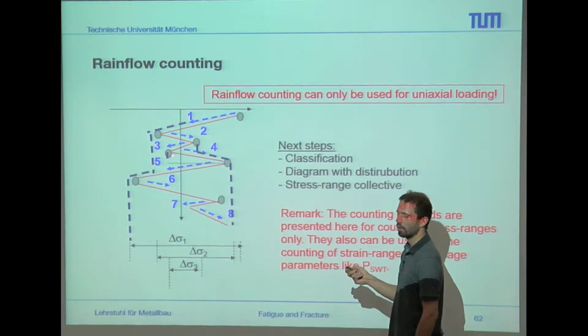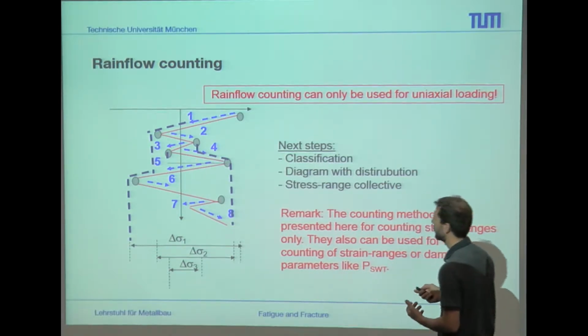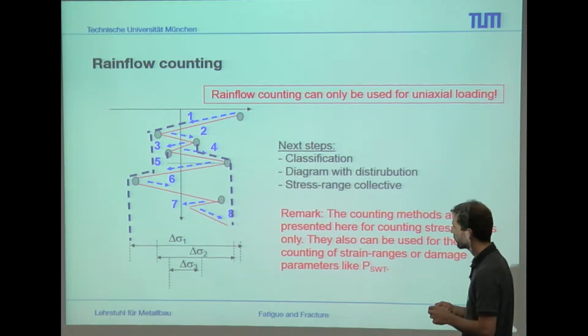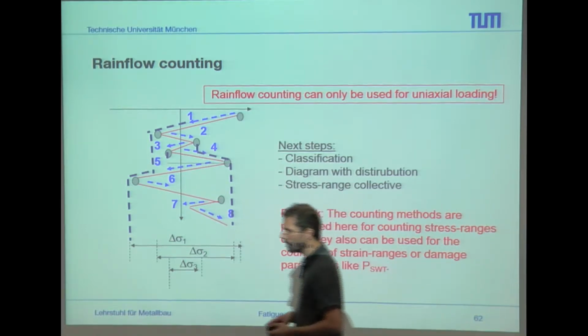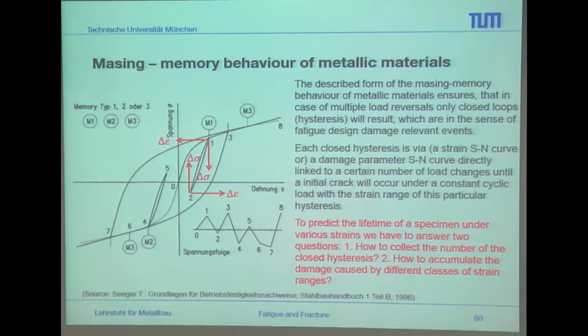And mainly this hysteresis here would start inside the other hysteresis, and this is not possible due to the Masing memory behavior, which we have here.